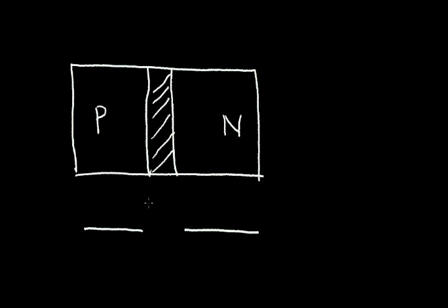So remember the capacitor. Here I actually have a capacitor. I have a P terminal, I have an N terminal. This region can be thought of as a plate on a capacitor. This N region can be thought of as a plate. So I have a plate and a plate. So this p-n junction has the characteristics of a capacitor.